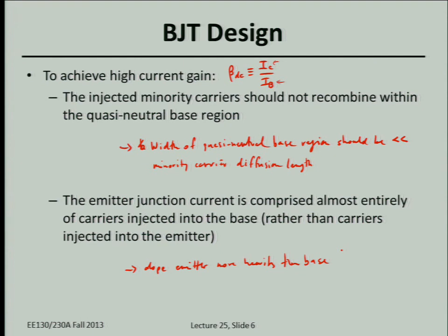Band gap? Zener, okay. Well, what happens just to the band structure of a semiconductor? Yeah, band gap narrowing. So what happens to the Ni? Ni increases, right? Because the band gap goes down. So if you dope too heavily, the band gap goes down, Ni goes up.